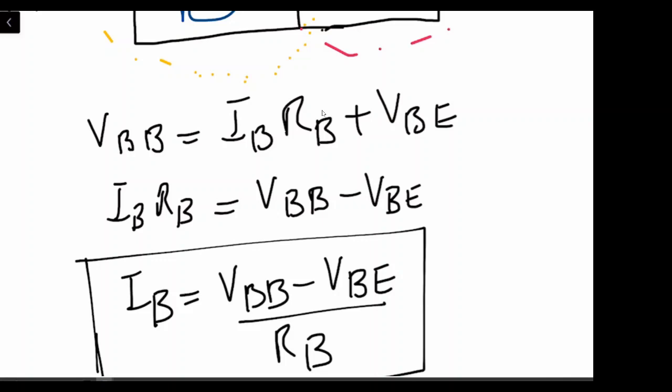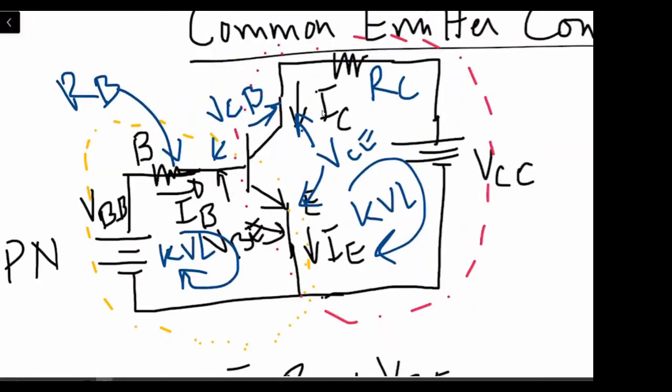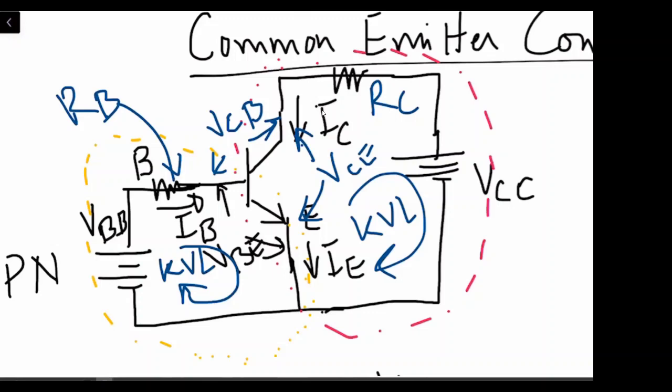Yes, sir. Okay, now taking a look at the output side of the circuit over here, we can see that VCC should be equal to ICRC plus VCE. Are you with me?